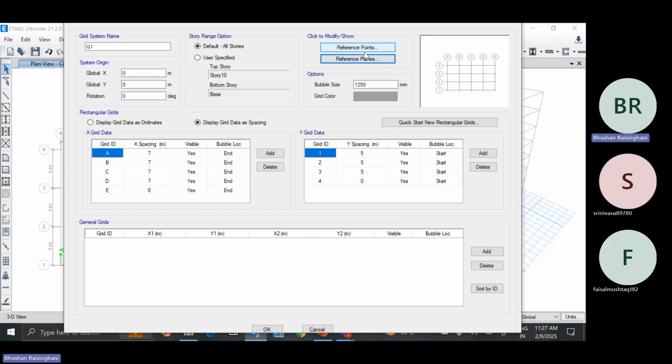Except at the perimeter or the full area. So a line load at the center of the slab cannot be applied until there is a grid or a reference point. So at those positions, you can generate the reference points, or you can generate a reference grid in plan.